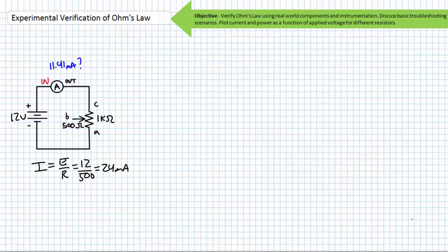I don't mean to go all Sherlock Holmes on you, but skills like deductive and inductive reasoning are essential to becoming a good troubleshooter. Deductive reasoning is top-down logic, where a conclusion is reached by applying general rules that hold over the entirety of your domain of interest, properties like Ohm's law. Inductive reasoning is bottom-up logic, where the conclusion is reached by generalizing or extrapolating from initial observations. Numeric literacy and your familiarization with your DMM is essential for the interpretation of initial observations. When deductive and inductive reasonings crash headlong into each other, you've found the problem.